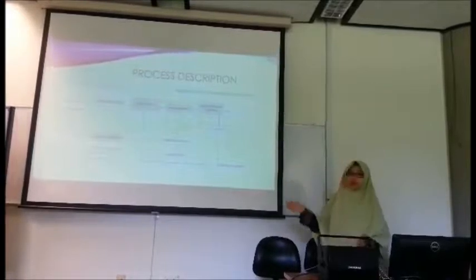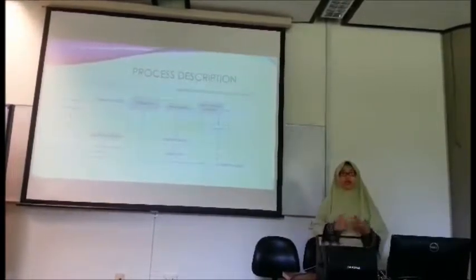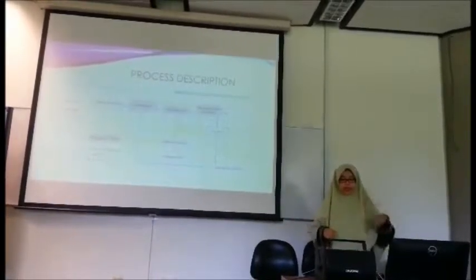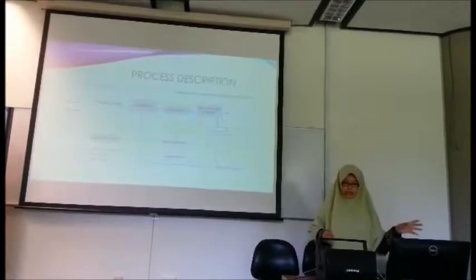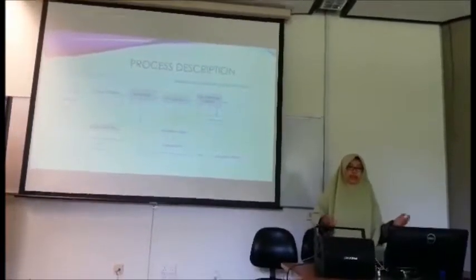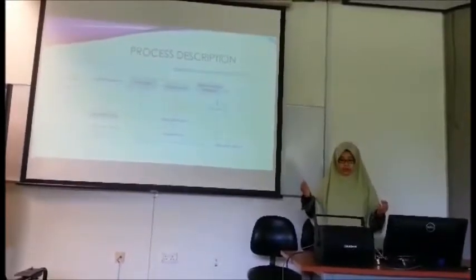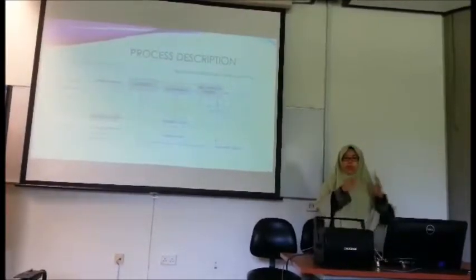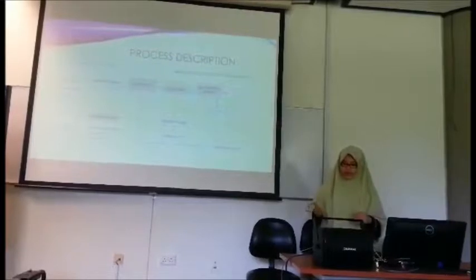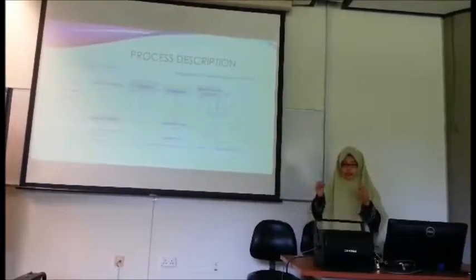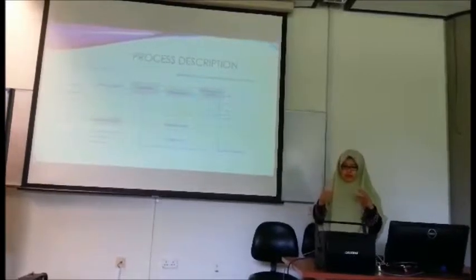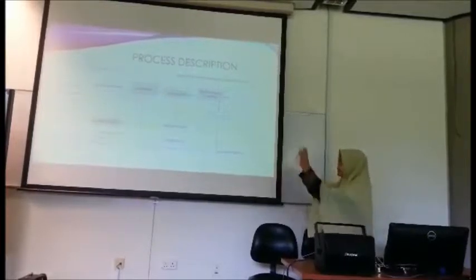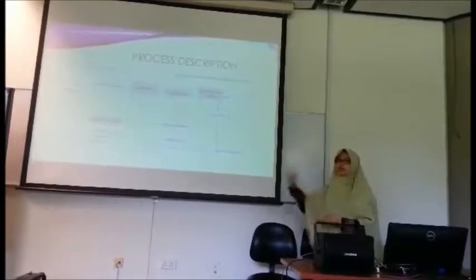For the concentrated product, it will go to the high concentrator, where here we use a forced circulation evaporator, and there the circulating product will flow through the heat exchanger where it will be heated and evaporated. Then it will go into the mechanical vapor recompressor, where it is used to bring down the wastewater volume by recovering most of the water in the waste. After that, as time goes by, the concentrated waste will reach saturation point and must be discharged. So it will be discharged from the bottom of the tank to the outside.